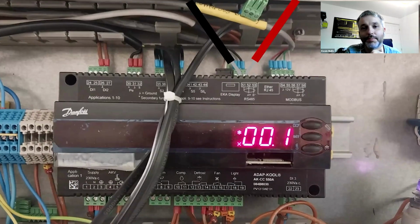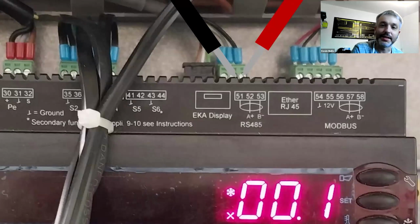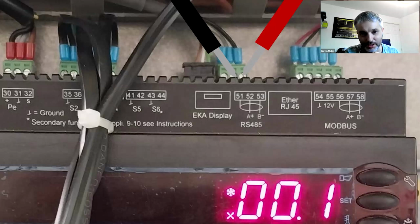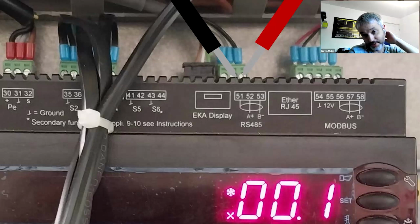The controllers are pretty solid on things like that. So we've just highlighted here the network. There's various different networks that Danfoss supports. In the UK, it's really common to use the Ethernet connection. Most other places, they like to use the RS485 with the Danfoss front ends. So you should have around about 2 volts difference between your A and your B line. The 485 standard is anything above 1.5 volts difference, so that it can see what's going on.